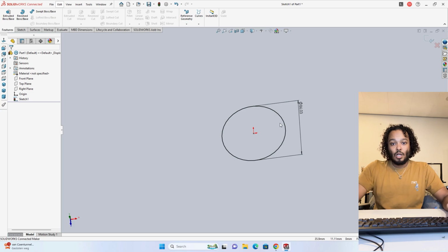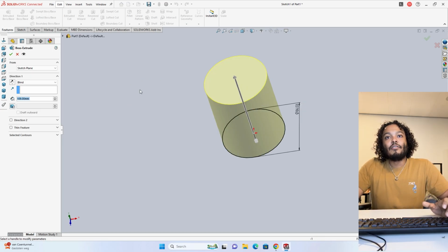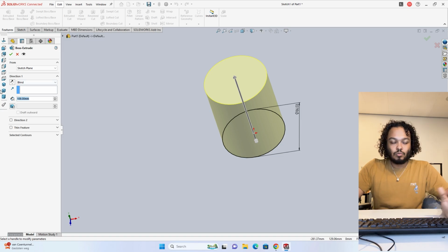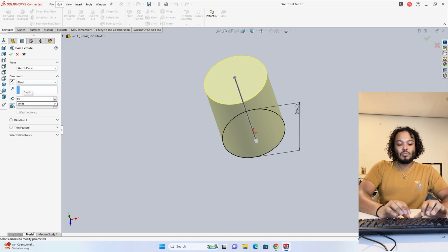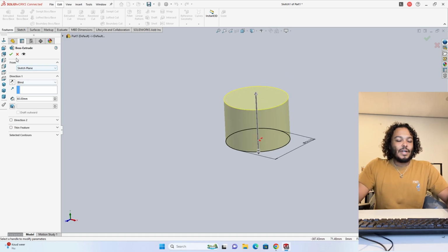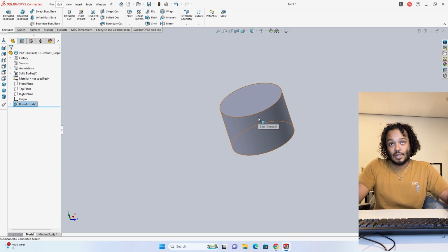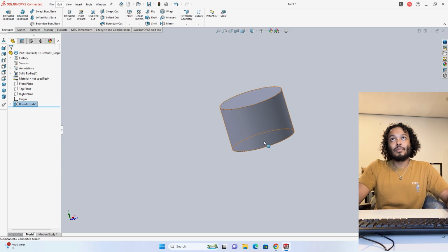So for a piston, it's actually pretty simple what you need to do in order to transfer this into something that could be used in the basic intro that I showed with the single engine piston block. So we're just going to extrude this circle sketch. And from this point forward, let's say we'll make it about 60 millimeters, I want to say. Seems about right. We can change that in a later stage. But this is the basic principal shape of a cylinder that we would need in the correct dimensions.